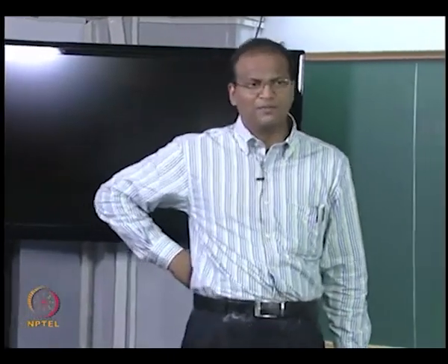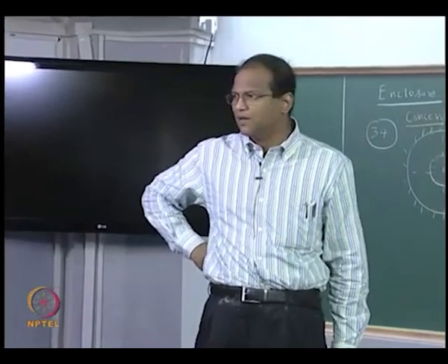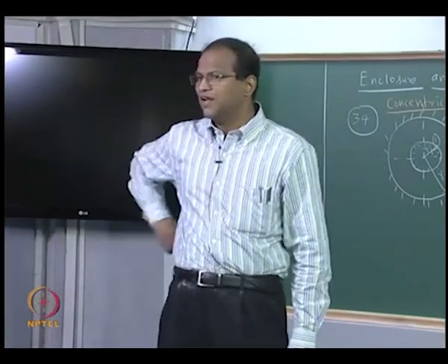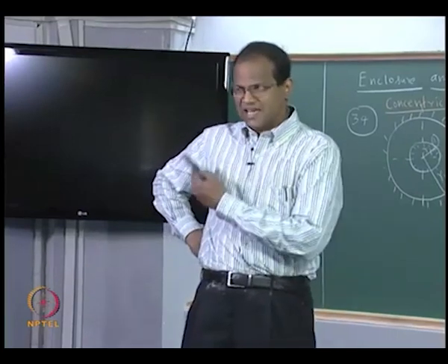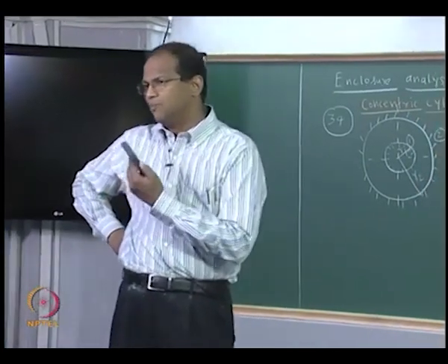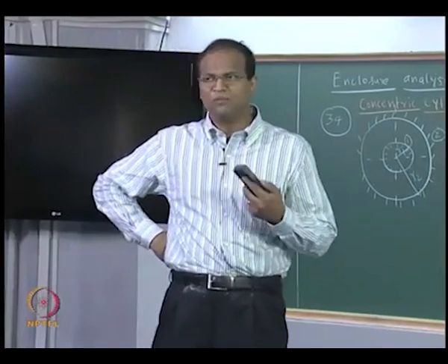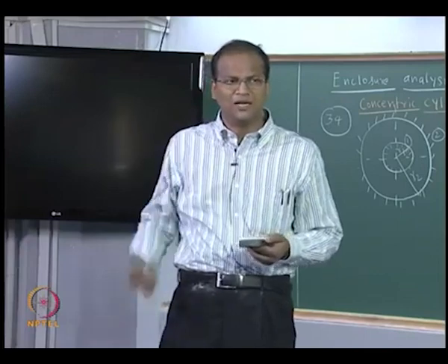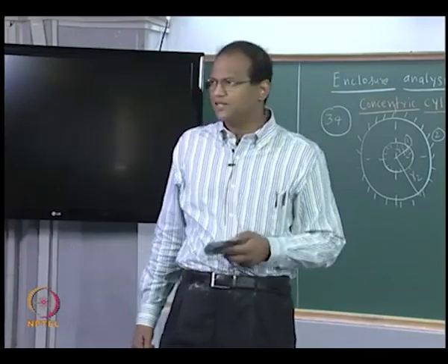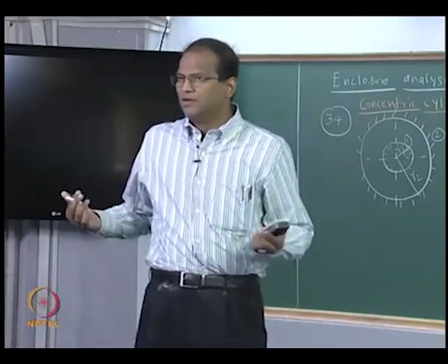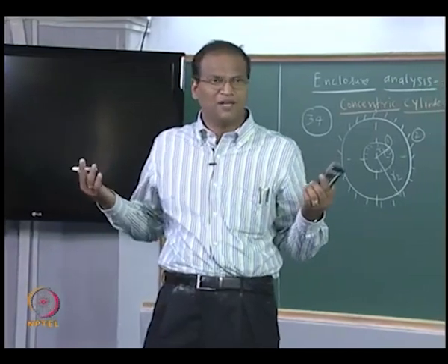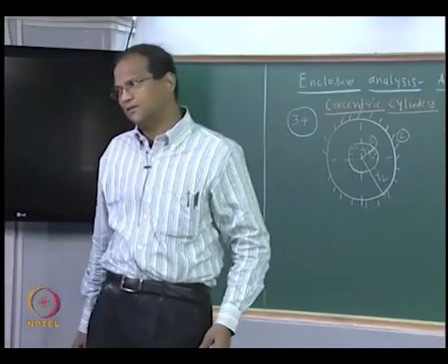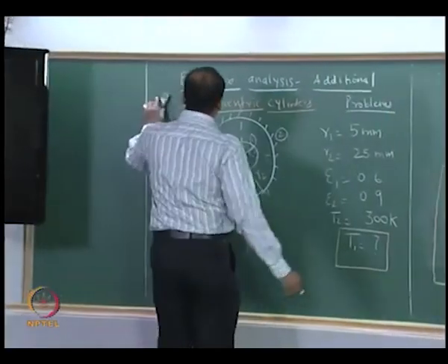You use the electrical analogy, the resistance network, but the resistance network will be very painful if you have a large number of surfaces. The advantage I told you is it can be scaled up, it is eminently programmable. We can easily write the radiosity equation in the computer, and very powerful techniques like the Gauss-Seidel technique are available where simultaneous equations can be solved. Mathematicians and engineers have developed good techniques for solving systems of linear equations. We exploit that. Okay, fine. Now the 35th problem.